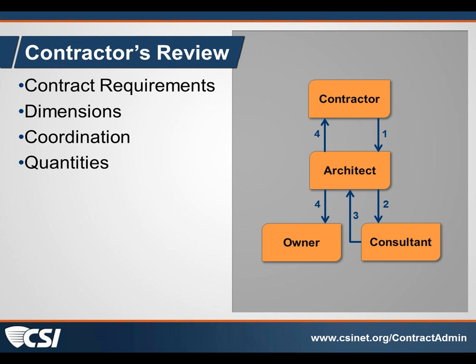And the diagram on the right here kind of shows the flow process. The contractor, a step prior to what you're seeing here, will get the shop drawings prepared by his subcontractor or the manufacturer supplier. He is to review them for the items we just talked about. Once he's reviewed and approved them, and oftentimes we get them where the contractor doesn't even look at them, they'll just pass them through. And if I can tell that that's happened, I'll return them and make sure that the contractor reviews them before I review them.